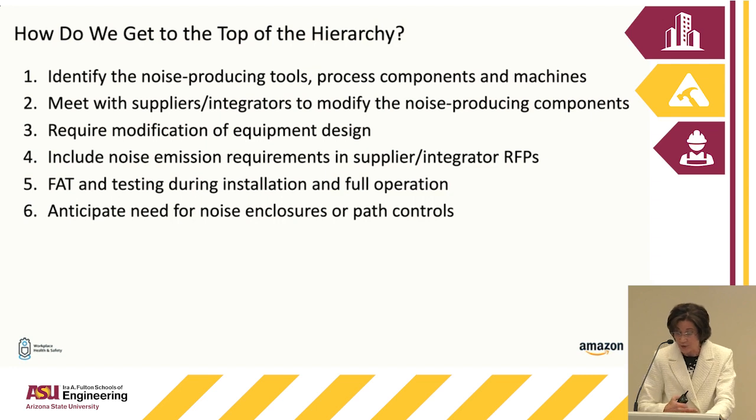Then we also have to include noise emission requirements in the supplier and integrator requests for proposals. So we have to give them our standards and say, you will comply with this. Tell us what the cost is going to be. Then we should ask them to do the testing during factory acceptance testing, or FAT, and then during installation, and then during full operation to verify that we have achieved what we've expected in our standards.